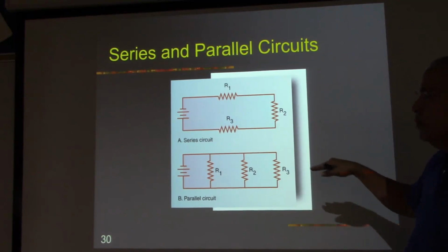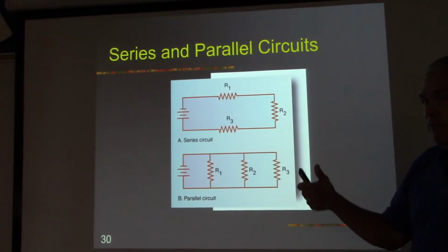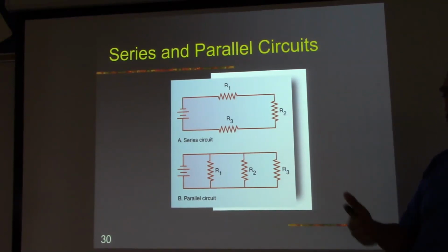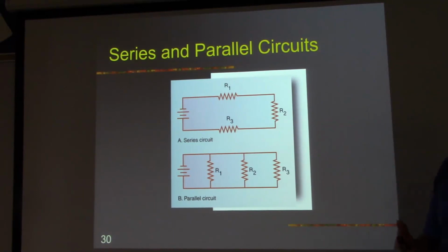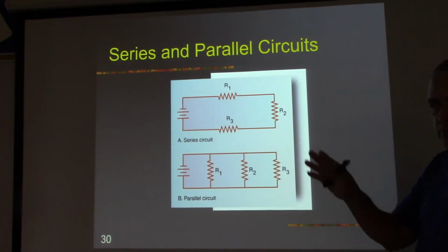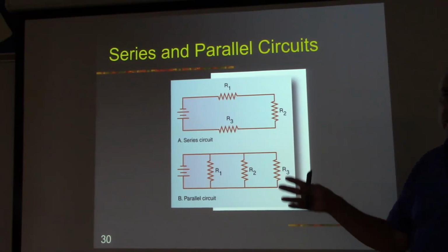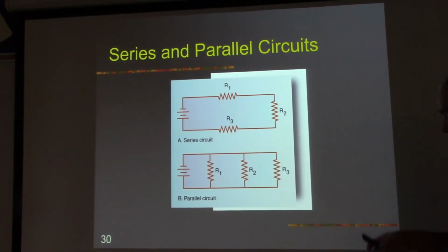If I'm adding more resistances and my voltage stays the same, then my current is going to go up to a dangerous level where I could maybe burn my house down. But before that happens, the circuit breaker is going to trip and cut off that circuit, and it's not going to come back on until I remove some of those resistances. So this is a safety method, circuit breakers, and we have those in our X-ray system too. If you try to run your X-ray tube with too much energy, you're liable to trip a circuit breaker.